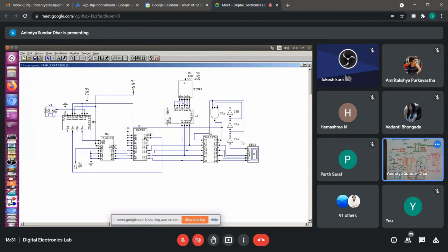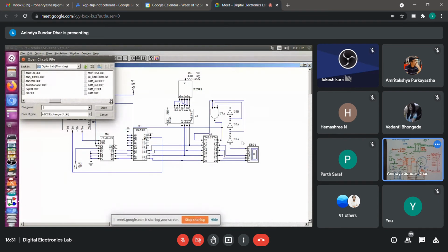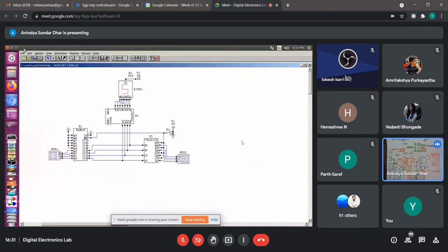Can you see that? I'm probably having another circuit also. This is a multiplexer. Just let me see whether I can find something else. I don't remember the names. No, this is the basic RAM circuit. This is how you can test a chip. This is the first circuit I made to check the chip, these RAM 1K. I used a hex keypad for generation of the address lines, and another hex keypad through that buffer for generation of the data, and then I'm just testing this one. But anyway, that is not the one.